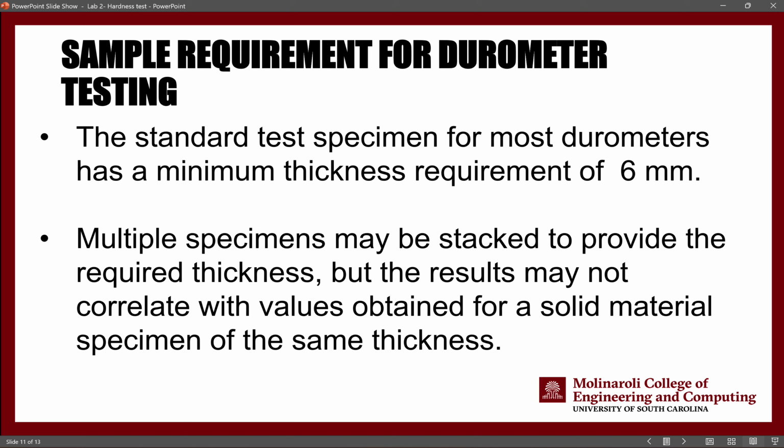You can actually stack multiple specimens on top of each other and measure the hardness value using that. But the hardness value you are going to get is not going to be exactly the same as the hardness value of a thicker material, because there are going to be layers in between all of the layers you have stacked on top of each other, like layers of dirt or air bubbles that are going to be between these stacked materials, which will affect the deformation of your rubber material.